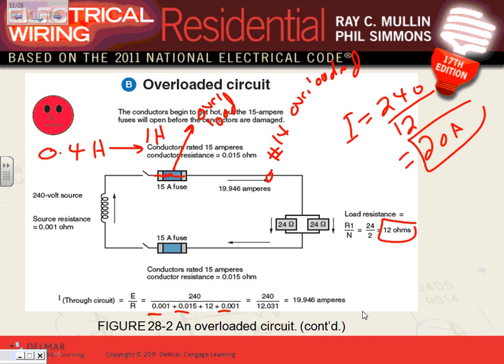Any question, guys, about overload? So it might take 10 minutes for this one to trip. Or 20 minutes, depending on the type of the circuit breaker, the setting of the circuit breakers, and so forth. And by the way, Nick, if you tell me, Chad, can you give me an answer exactly 20 minutes or 30 minutes? I can, if I have the current characteristic curve of this fuse. I can tell you if you load it with this amount of amps, it will trip in 20 minutes. Obviously, that's what we predict an equipment might. So there's a tolerance plus or minus that 10%, 20 minutes plus or minus, say, 10. There's a tolerance, as you know, Chris, for equipment.